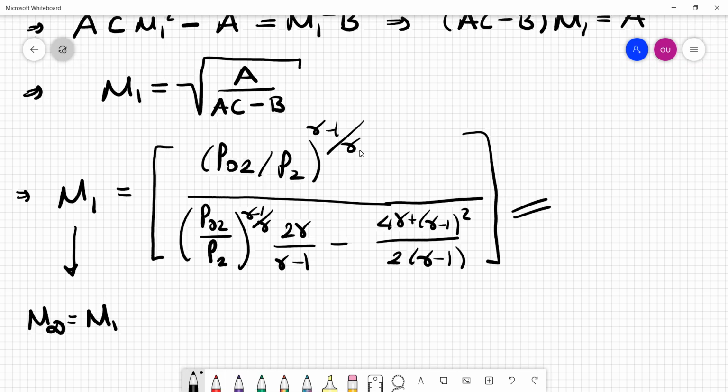And all this equation is basically coded into the flight computer of the aircraft. So depending on what it measures from its pressure transducers connected to the stagnation pressure hole and the static pressure hole, it calculates this ratio basically.